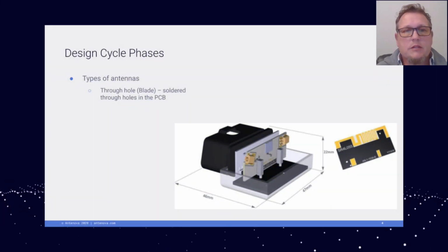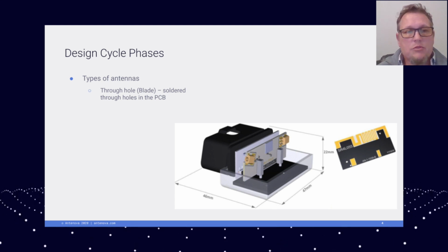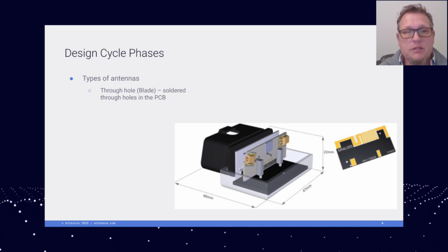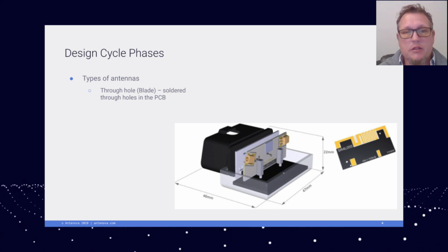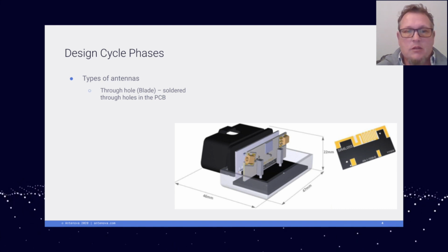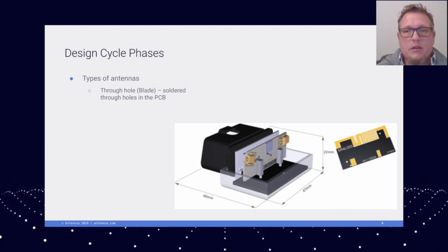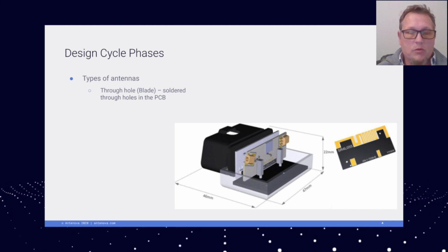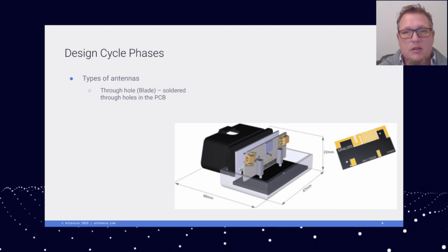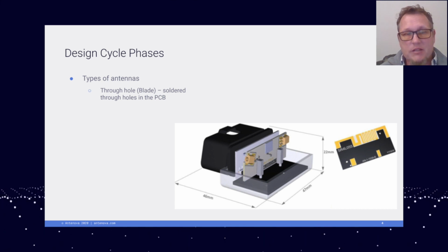The next antenna type I'd like to go over is the blade antenna. Blade antenna is used to shorten the overall device length when your device needs to be small, such as the OBD or onboard diagnostic devices. These blade style antennas require the interaction of a pogo pin or something to contact between your main PCB and some pad landing points on the blade style antenna.